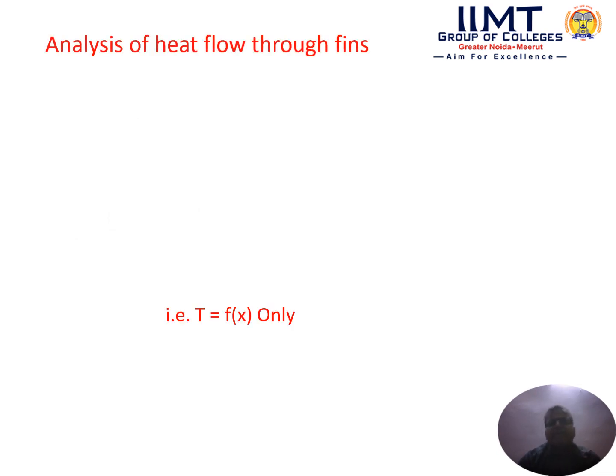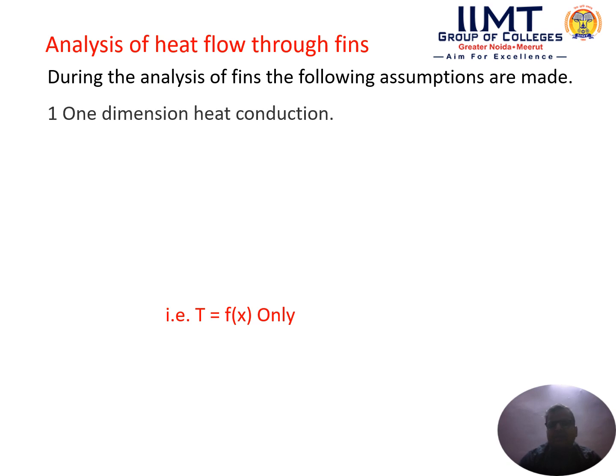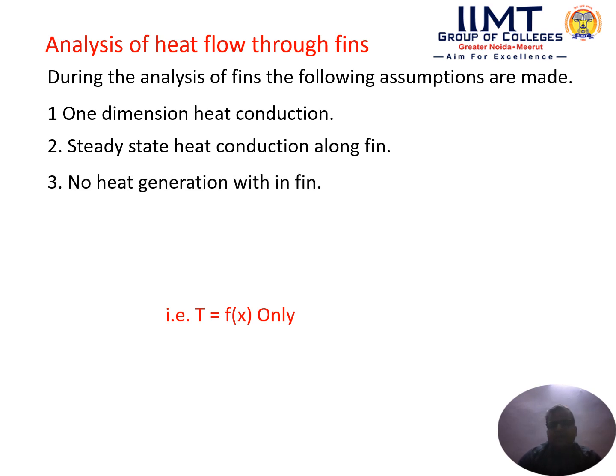Next one is the analysis of heat flow through the fin. During the analysis of fin, we have to take some assumptions. Number one is one dimensional heat conduction, and that should be along the length of the fin only. The flow of heat should be steady state, along the length of the fin. And third one is there should not be any internal heat generation within the fin.